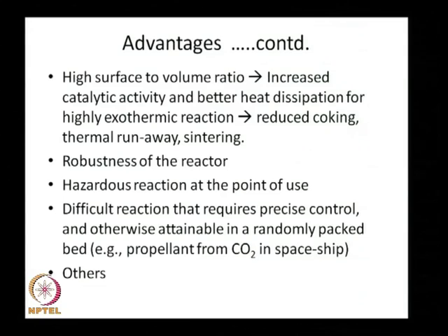If you load in one place, again you think of a probe volume. If you load your catalyst randomly, suppose as the two streams enter into a randomly packed bed of catalyst, it is encountering the catalyst on the way. In some volume, they find that the catalyst loading is much higher, and in some volume they find catalyst loading is much lower. So, accordingly the conversion also would be guided by the amount of catalyst it encounters.